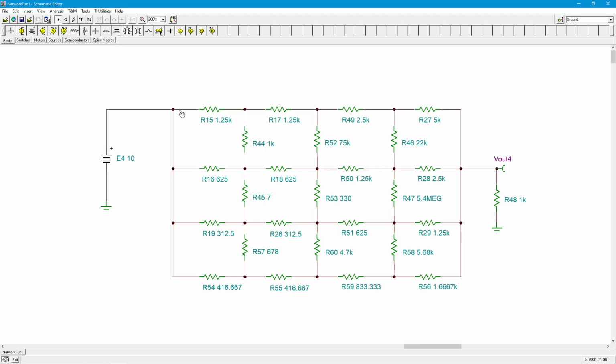So the easy way to do that is you figure out, okay, look, these are all going to be in series. So this is like a 10K, and this is like 5K, and this is 2.5K. And I just have to find the fourth combo that when I put them all in parallel, I get 1K, right? So you can just figure out the conductances. 10K is 0.1 millisiemens, and you just work your way back, adding up the pieces until you get to 1 millisiemen, which is 1K, right? So let's do an analysis.